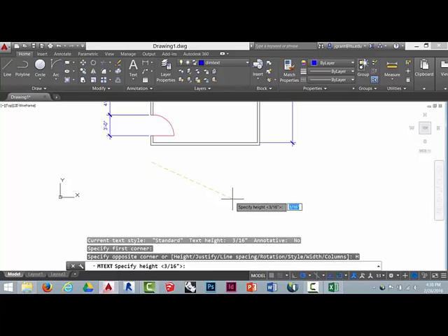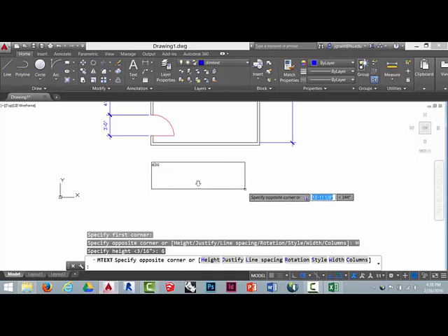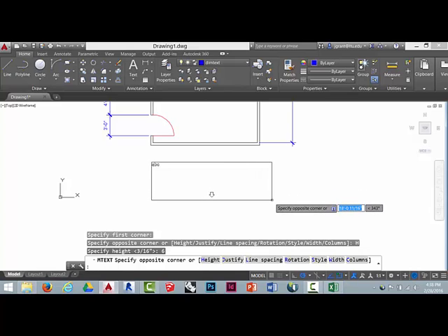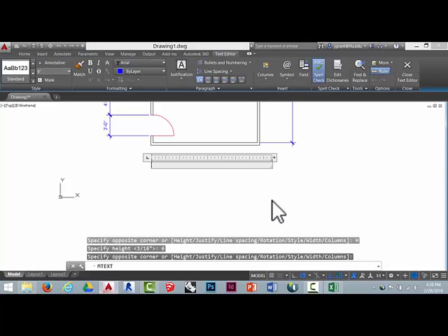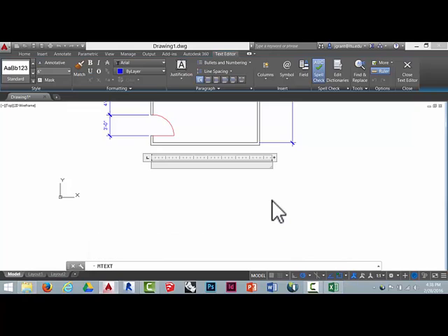I'm going to use 6 inches because I'm taking the 1/8 inch text, multiplying it by 48, and getting 6 inches. So I'll type in 6 and enter. And then I'm going to pull my mouse over and pick to establish my small little editing box, multi-line text editor inside AutoCAD. You'll see that the ribbon changes completely. So now with my caps lock on, I can call this floor plan and start to put the rest of the information.